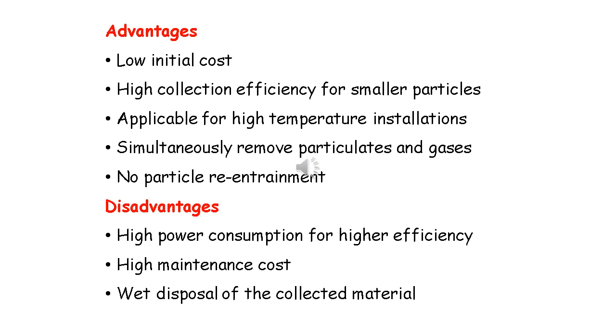Advantages are: the scrubber's initial cost is very low, and hot gases can be cooled down. That means it is applicable for high temperature installations. And corrosive gases can be removed and neutralized. The separated gases, through contact with the aqueous chemicals, may produce useful byproducts such as chemicals and fertilizers, etc.